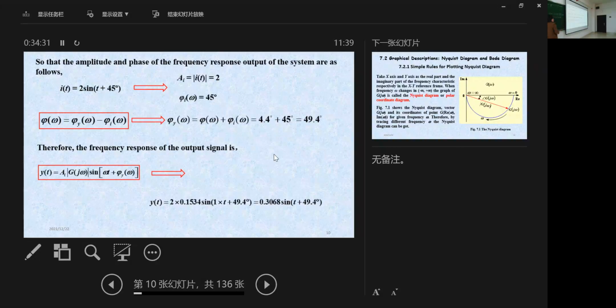Look, this is Ohm's law. The voltage over R equals the current times R. So this is the voltage, right? And plus another voltage here, the voltage over L. What's the formula to calculate the voltage? L di/dt. Yes. And another voltage is what? Yes. So, understand? Yes, I understand. And what is Uo? The voltage of C, right? Very good. So you can write those two equations.